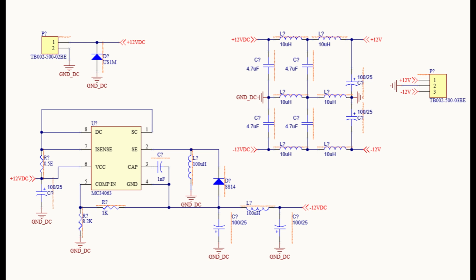To simplify the schematic and avoid long crossing wires, off-sheet connectors can be inserted. Off-sheet connectors can be placed using the shortcut P, followed by C. These connectors help organize complex designs by clearly indicating signal flow between different sections of the schematic. Using off-sheet connectors greatly improves readability and reduces visual clutter.